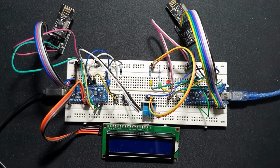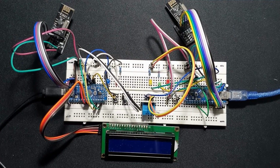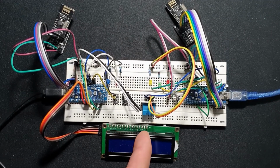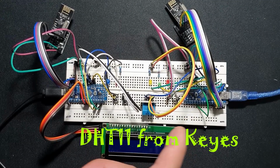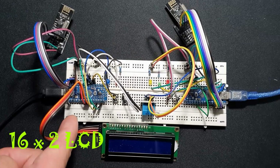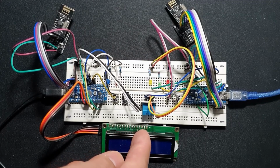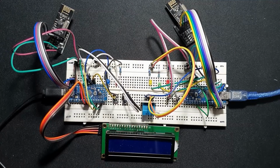I have set up bidirectional communication between two Arduino Nanos using the NRF24L01. I have the DHT11 humidity and temperature sensor on the transmitter and an LCD hooked up to the receiver. Readings from the DHT will be sent to the receiver and displayed on the LCD.